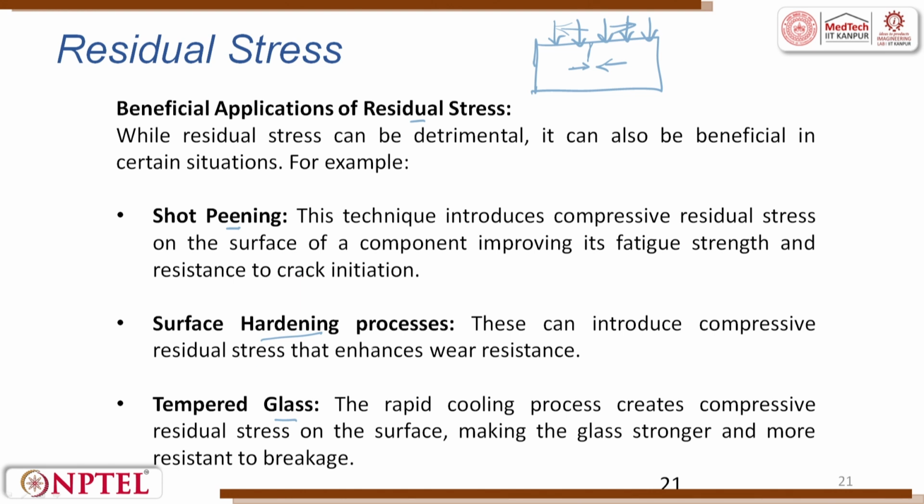Surface hardening process: this can introduce compressive stress that enhances the wear resistance. For example, you heat it and quench it. When you heat it and quench it, what happens? A hard layer comes on the surface. When the hard layer comes, the wear resistance improves.